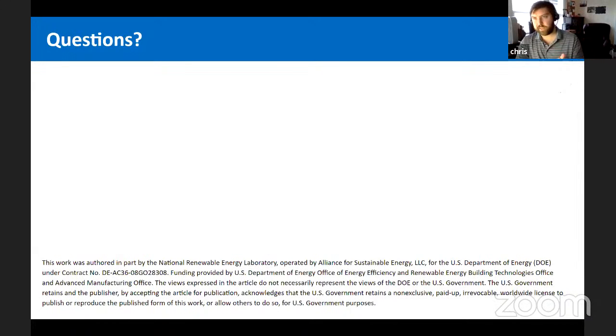And maybe I'll just add that if you are starting from no information at all except for, let's say, the geometry, the building program, and the year when things are built, you can at least construct something using the ASHRAE 90.1 or ICC templates that are included with the plugin. Granted, that's a very coarse start where you're just starting from a best guess, and then as Ben mentioned, as you get more information from assessments or surveys or other data sets, you can refine that and make that more accurate to what you need.